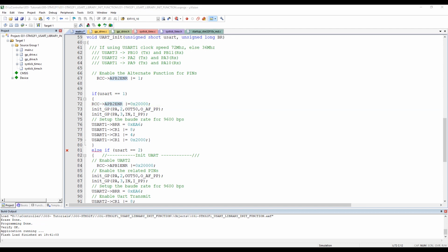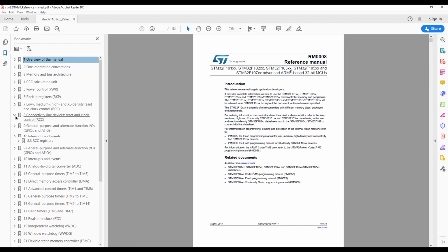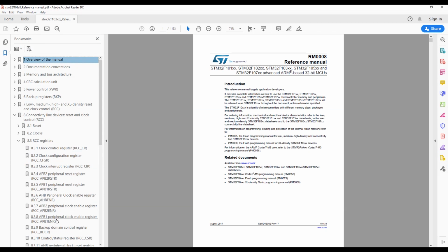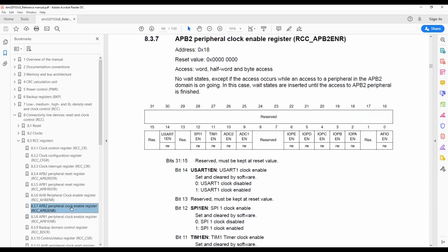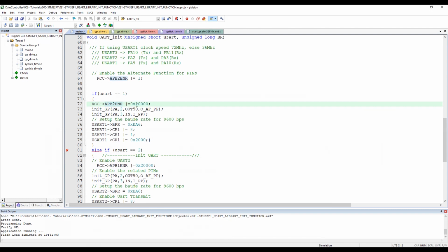And let's look for which. So let's go, reset clock, APB1 enable, and where are you? Yeah, so it's in the 3rd byte, 2nd bit. Good. No, sorry, this is APB1. We need to go APB2. Yeah, then UART1 is the 2nd byte, and almost the last bit. Okay, perfect. So to put it, we go back here. So it's not this number, but we put here 4. So that's the 2nd byte, and the before-last bit.